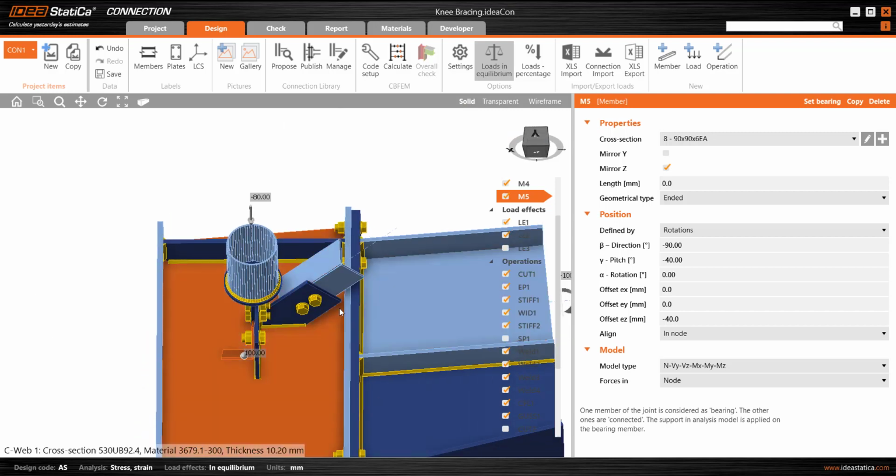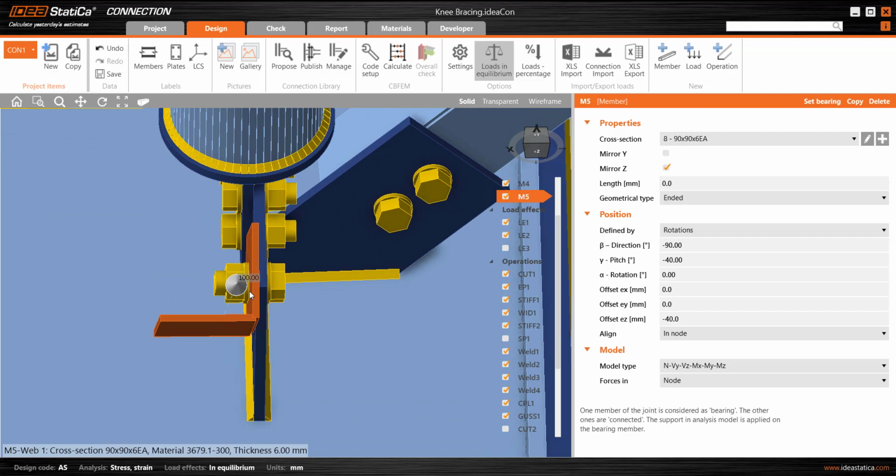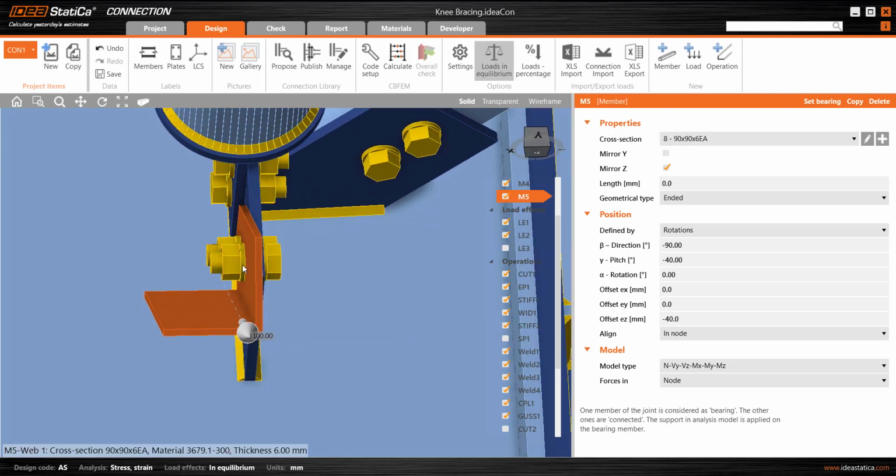And particularly if the shear center is quite distant from the centroid, you want to consider the eccentricity. And of course, for angles, the shear center is at the intersection of the legs. The centroid is a little bit of distance away. So this type of eccentricity can be quite significant in causing excessive lateral bending and plastic strain and deformations and so forth.